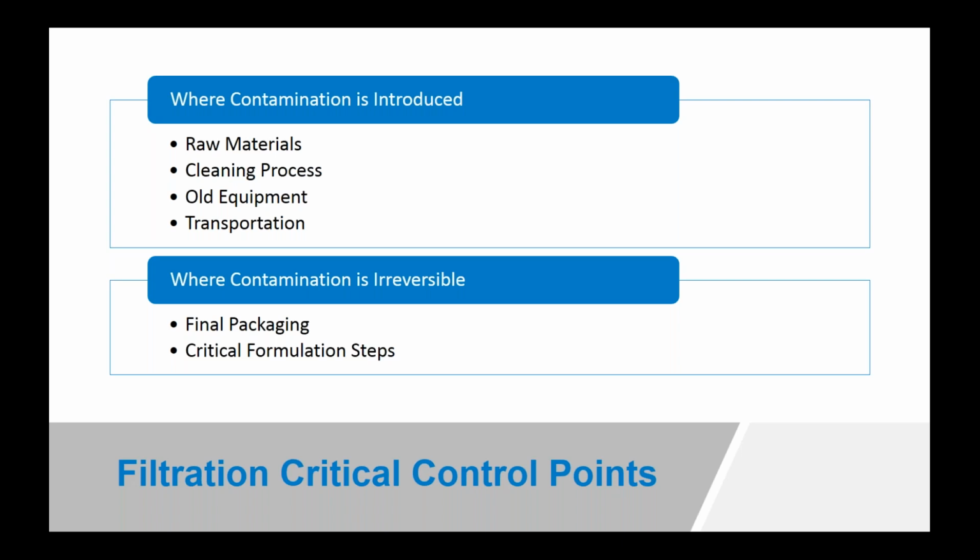And that's fine, but what happens when the city decides to do some work on the street next to the building? And now you're producing not only compressed air, but also compressed diesel exhaust and cement dust and asphalt smells and things like that, and applying that mixture directly to the food product or packaging surface. So things like this are relatively unlikely and infrequent, but it's a real threat, and it's happened many times in the past. And again, the point is that preventing this from happening is better than reacting to it after it's happened.